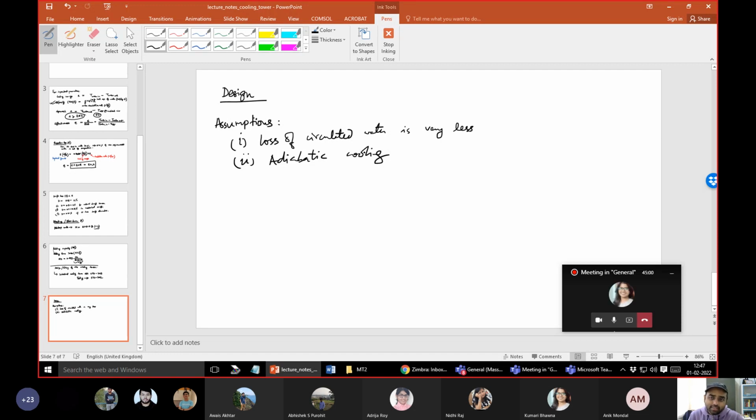Partially, that also comes from the engineering practice of having makeup water so that the water flow rate remains almost constant. The makeup water is continuously monitored and controlled. It cannot stay the same, because there is continuously some loss due to evaporation, and if you are continuously bleeding out something, then you have to continuously supply makeup water.